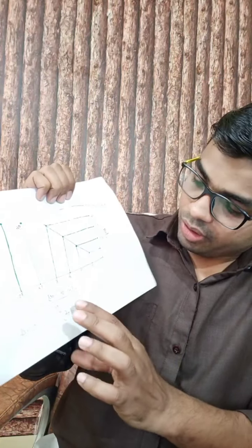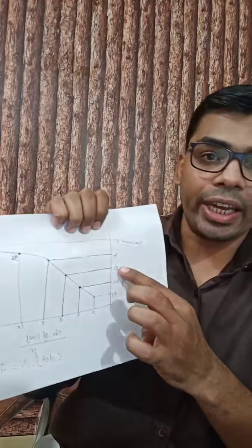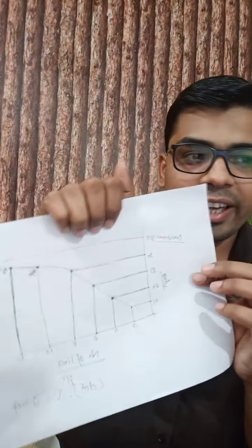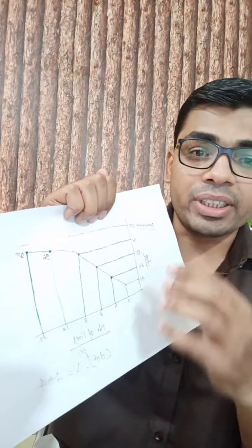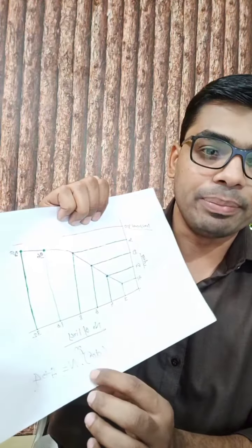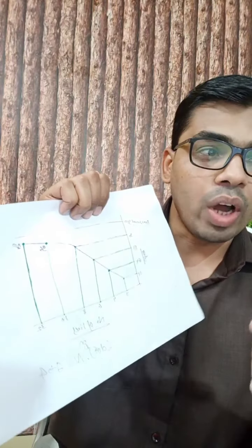And also obviously if you go for fine mesh, your degrees of freedom will increase, right? You'll see large degrees of freedom here. So I'll show you one graph here. Look at the graph, right? In this graph, you can see the number of lines versus the area. So solution time drastically increases, and basically it is directly proportional to the degrees of freedom. Okay, so n equals 1 to 4.